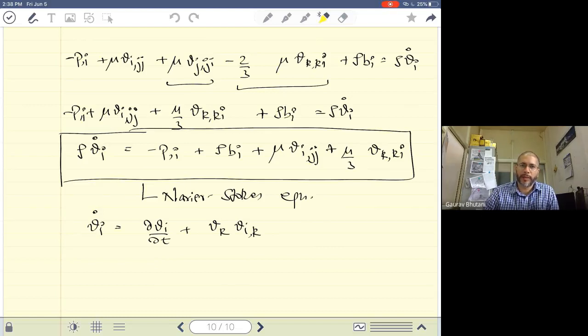the form drag acting on the wings, and then the velocity field typically helps us calculate the shear drag or the friction drag on the wing. So that helps us calculate the total drag on the solid object, or the wing, in this case, the aeroplane wing inside the flow field. Okay, so pressure and velocity help us. If you know about these fields, we have characterized the flow completely.